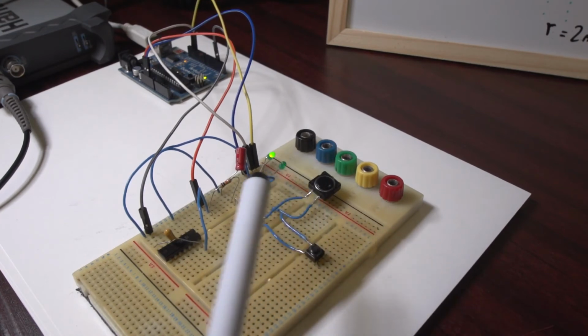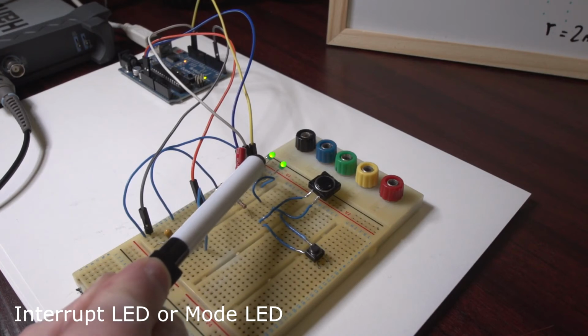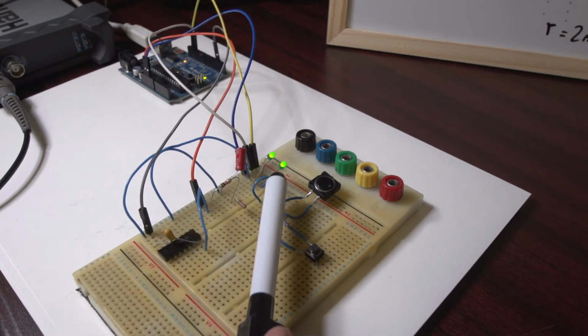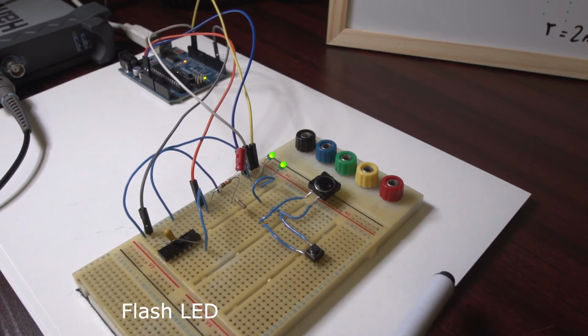A couple of LEDs here. The one that's on constant at the moment is the interrupt status, if you like, the fast or slow mode indicator. At the moment we're in fast mode because the LED is on. Then we have the flash LED, which, because it's in flash mode, is switching on and off in 100 millisecond cycles: 100 milliseconds on, 100 milliseconds off, and so on.